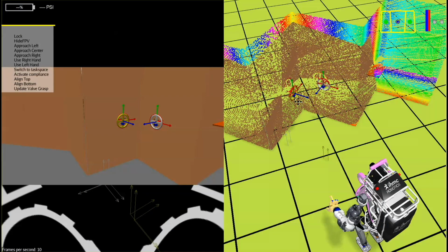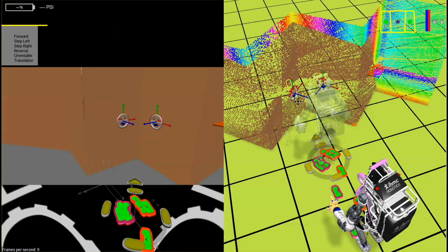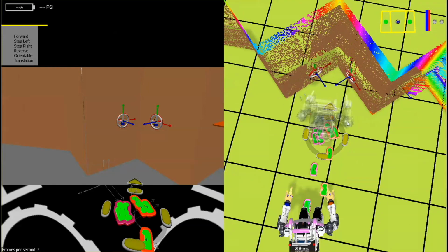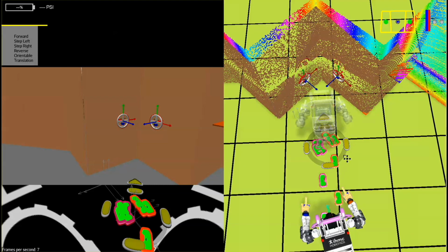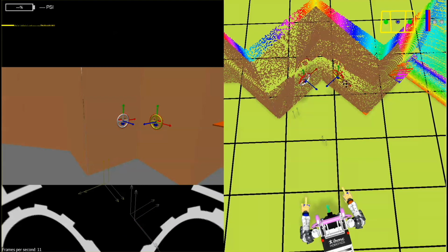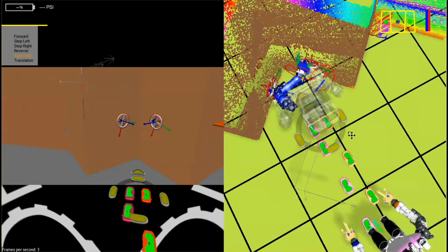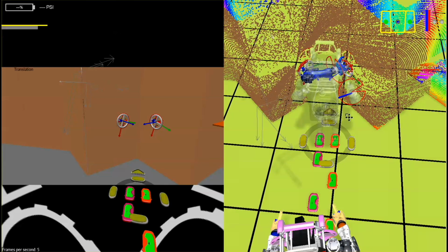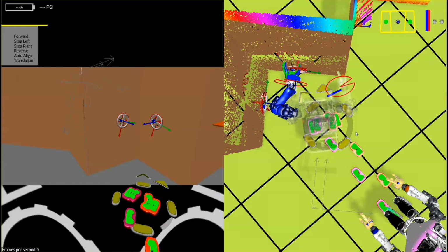Here is our Atlas robot standing in front of a valve instead of a hose, but the principle is still the same. You will see some engineered solutions as to where to stand to manipulate a particular valve. While the first option is all right, the second option actually collides with the corner. It would be nice if the robot could reliably avoid all obstacles, but if it cannot, the human needs a way to understand the constraints and adjust the robot's position. This interface allowed the human to have the robot virtually grasp the valve in order to understand proper placement and to stand and have the range of motion necessary to turn the valve completely.